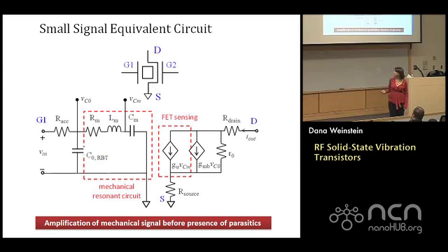For the device people among you, a basic model of this structure looks something like this. We had to come up with a new symbol. Looks kind of like a crystal, kind of like a transistor, pretty cool. All right, but it's a 4-terminal device. So here I have my drive gate, gate 1, which is basically applying a voltage across a capacitor and generating an RLC resonance, essentially a mass spring damper system, right?